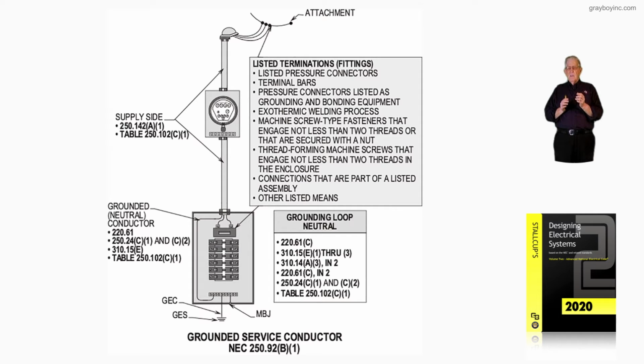Now, 70B suggests check the circuit mapping, 408.4 of the NEC. And if you have more neutral loads than you have phase-to-phase loads, then you know the neutral is going to be larger than what's required by table 250.102(C)(1). 220.61 would be the section that would be used, because it would be used to calculate the neutral load.